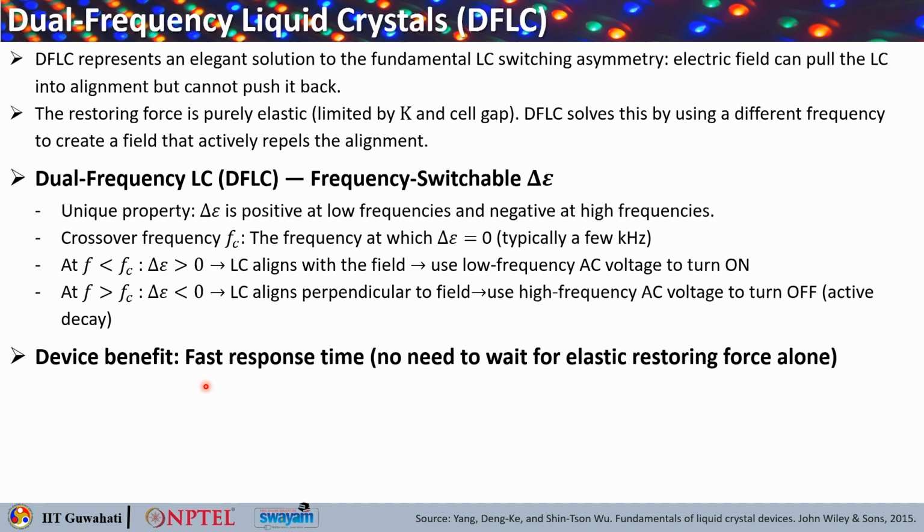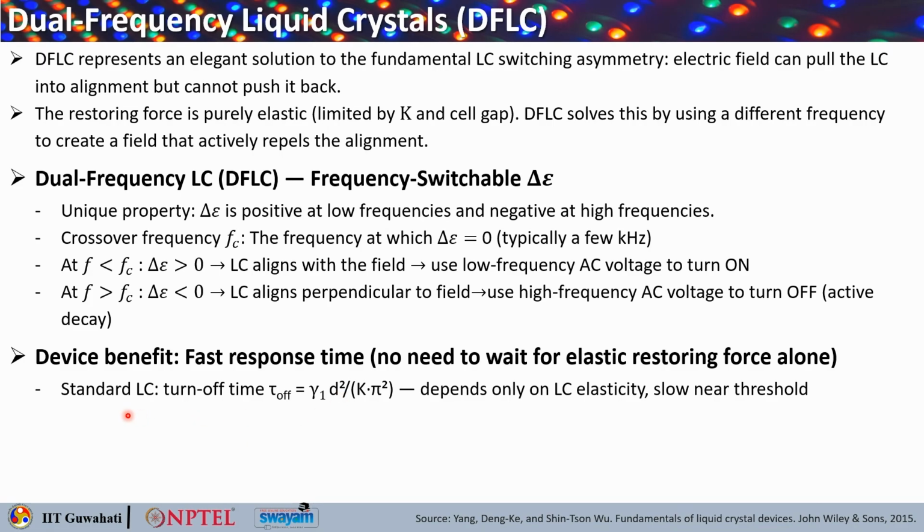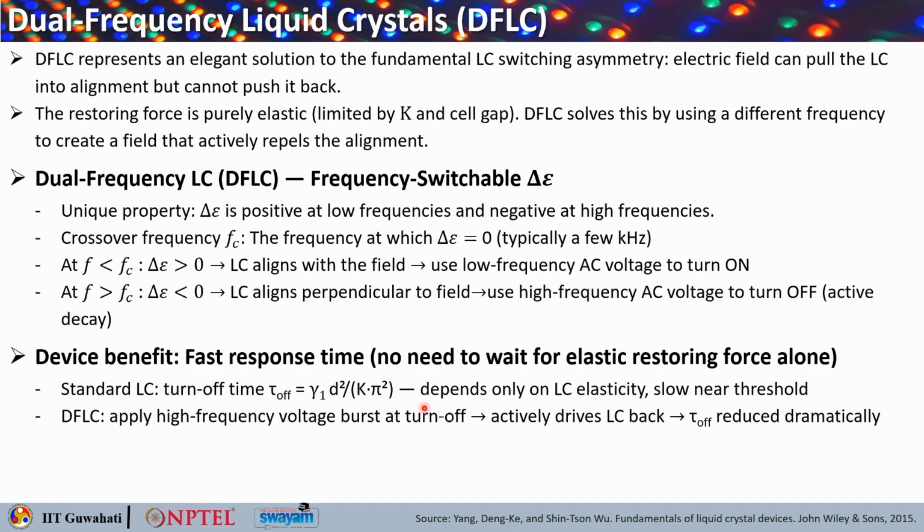So, what is the benefit? You get fast response time and you do not need to wait for the elastic restoring force alone. For the standard liquid crystal, the turn off time is given as tau off, that comes from the viscosity and the elastic constants, like gamma 1 d square divided by K pi square. So, it depends on the liquid crystal elasticity and it is slow near the threshold.